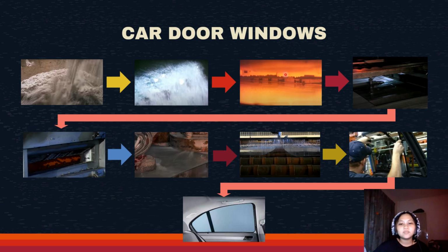The molten glass mixture is then left floated on liquid tin before being cut and shaped into several rectangle flat pieces. A computer-controlled tungsten carbide wheel scores the required shape afterwards. Next, a flame is directed towards the glass to create a thermal stress to crack along this score. The edges of the newly cut glass are subsequently ground and washed, and then toughened by being floated on a hot gas with a temperature of 630 degrees Celsius.